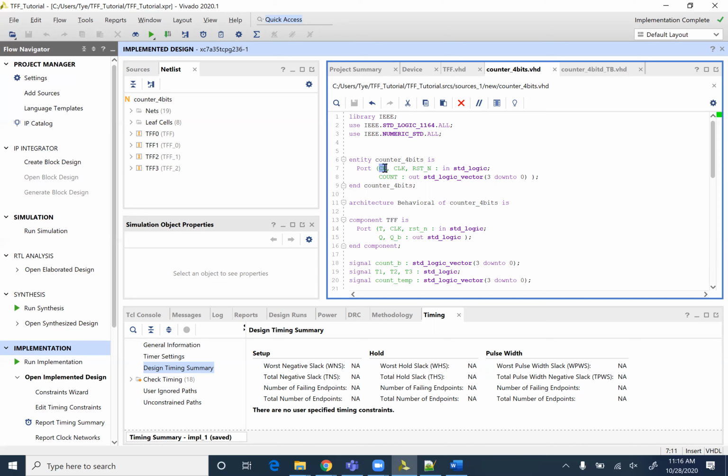So then you have to specify that in order to use a clock, we need to take it from outside in the real world. Because we use what are called crystal oscillators for most of our good clocks. We actually use crystals to make good clocks. And then we use something called a PLL, or a phase locked loop, in order to use that good clock to generate higher or lower frequencies.